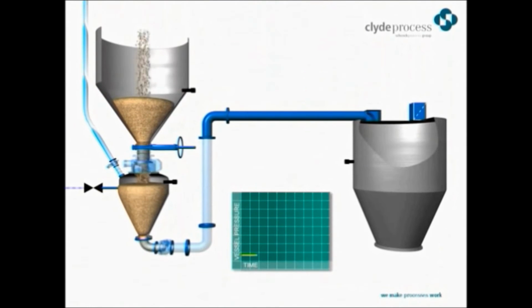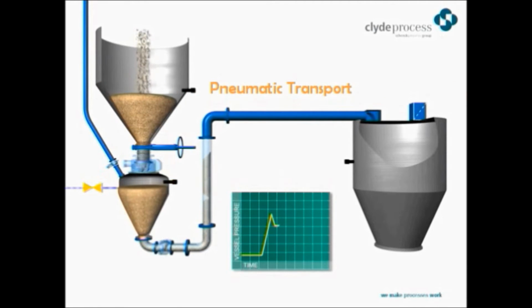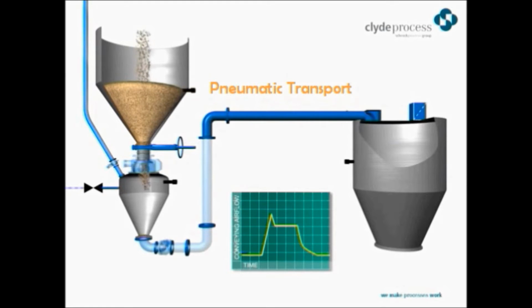For the next system, the switchgrass is transferred from the hopper to the fluidized bed dryer through an enclosed pipeline called the pneumatic transport system. With the help of the air mover, which is a blower, as the source of air, a combination of pressure differential and the flow of a gas provides force to move the switchgrass to the next system. As the switchgrass from the hopper is originally fairly dry, this system is suited for the particle transfer.